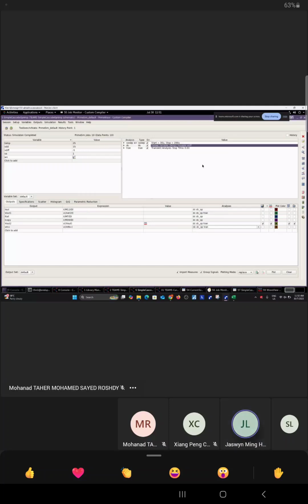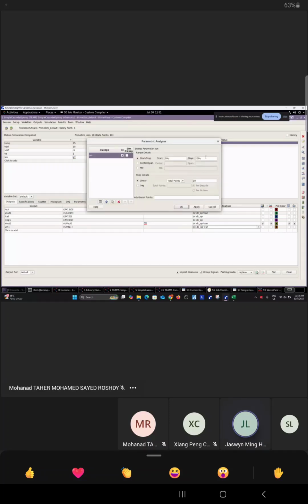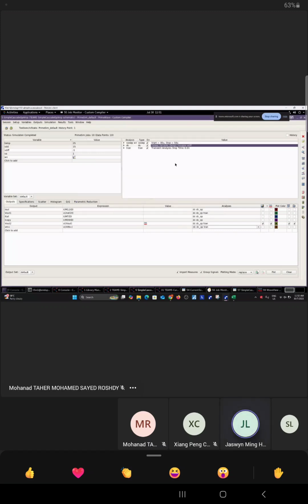Okay. 50U. Yeah, 10 points. Good enough. Yeah, now this is another way you can do to make your simulation much faster. Everything on the pipeline, just run it. It's going to be 2U difference between each of them. And then I would say for parametric sweep, going into the second level is good enough. If you go to the third level, the number of graphs you see will multiply a lot.